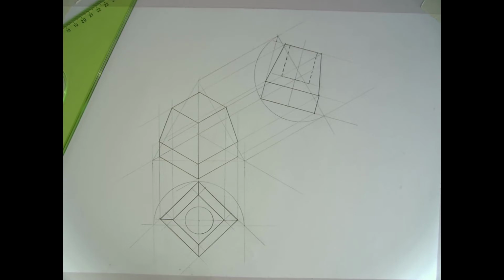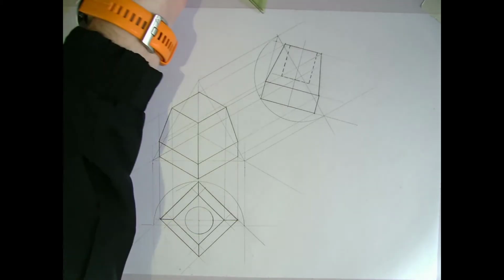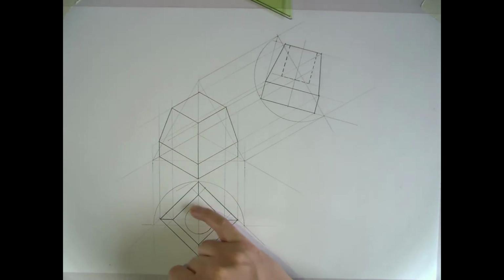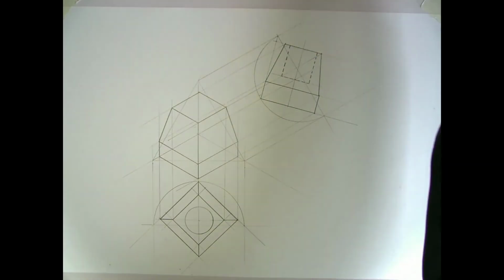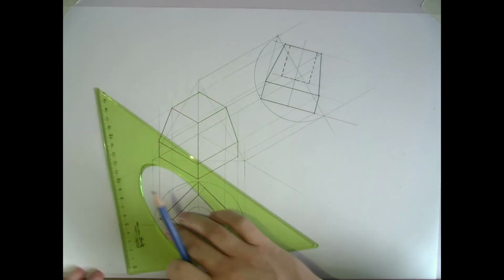So that's what we're going to look at now, drawing the axonometric projection of the circular hole, the cylinder, up on top of this here. So now what we need to do is we're going to divide this circle up into a number of points, because we had points for this corner and this one and this one. But for this circle we don't have any points. We need to create points on that circle. To do that, we're going to divide it up. Generally we divide it up into 12 parts, but we may not need 12 parts here today.